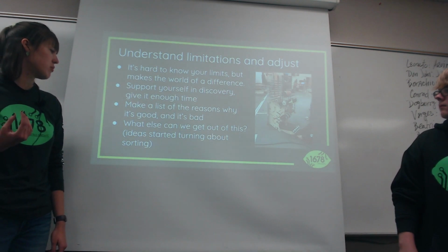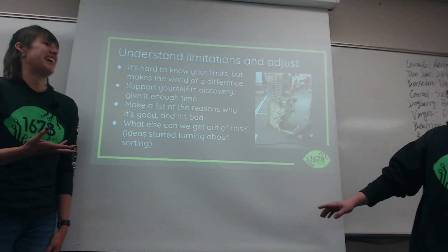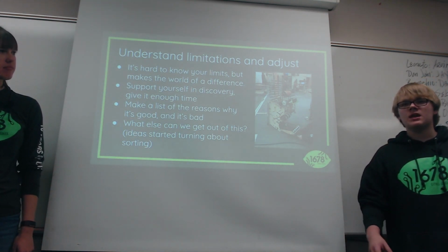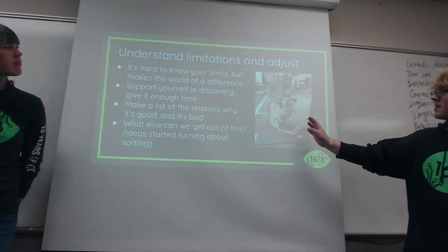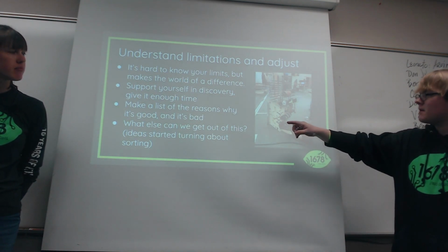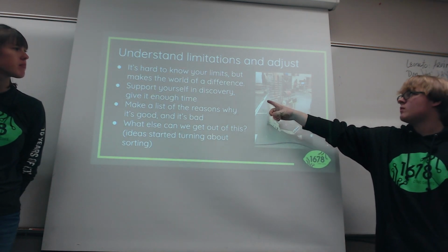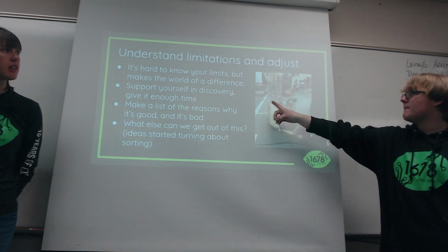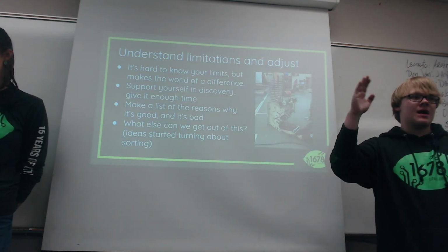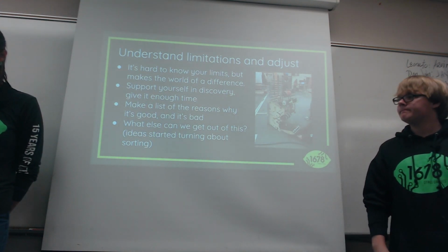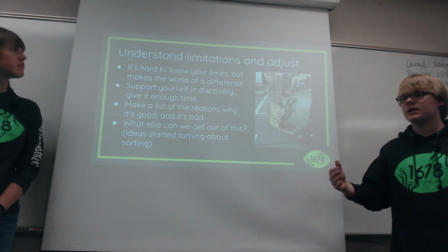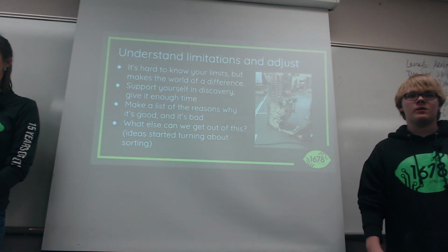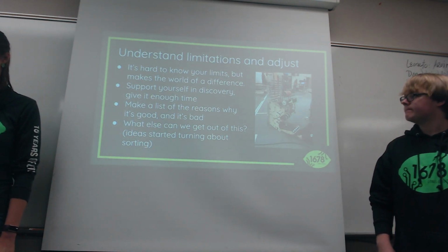I had another point that I was going to bring up, but one other thing that's really cool about prototypes is, if you're building something like an alpha robot, it's okay to give yourself leeway in how it works. This isn't as common on this one because we didn't really have time to think about that, but for the shooter, we basically have this web of holes, so we don't really know how compression is going to go on the shooter. So we had a bunch of different holes, so we could move the backing around and find out what compression was going to work better. So give yourself leeway, even if you're making a prototype robot. Still give yourself the opportunity to experiment, find out what works, find out what doesn't, and most importantly, run a lot of tests.